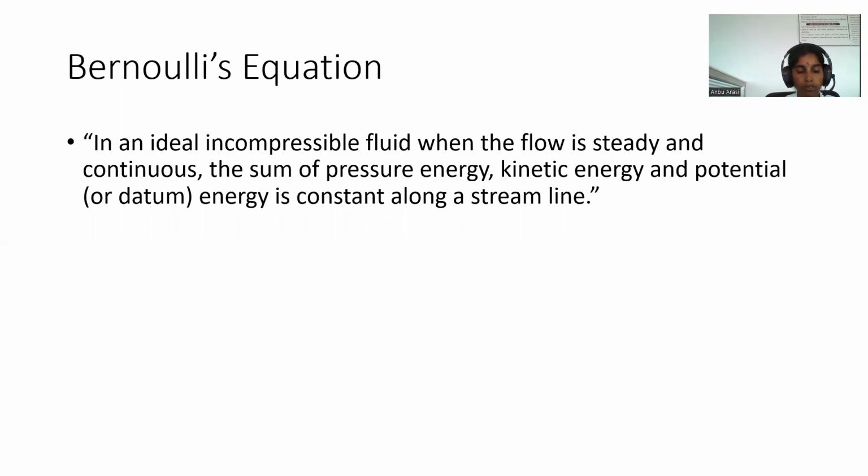The dynamic behavior of the fluid flow is analyzed by Newton's second law of motion, which relates acceleration with the forces. The fluid is assumed to be incompressible and non-viscous. Equations of motion. According to Newton's second law of motion, the net force acting on a fluid element in the direction of x is equal to the mass of the fluid element multiplied by the acceleration in the x direction. Then it is Fx = m ax.